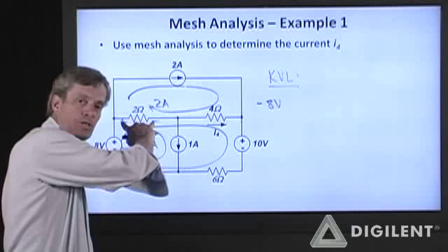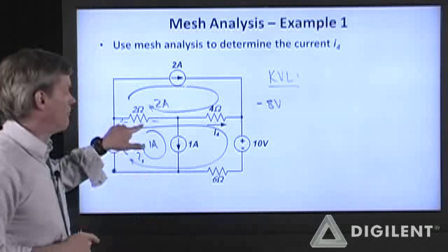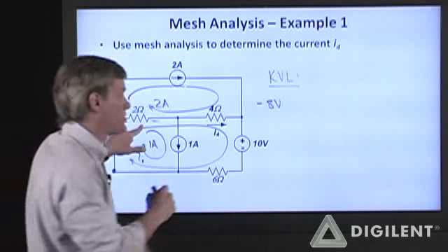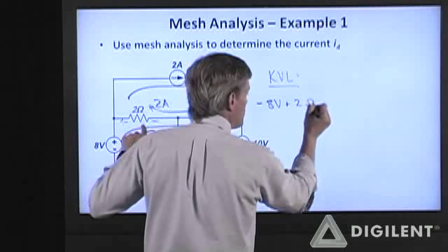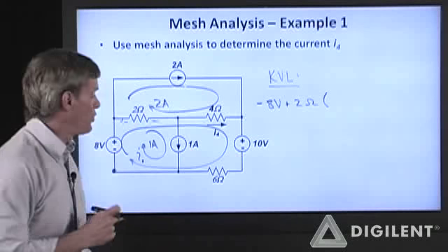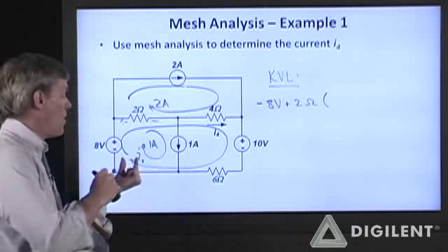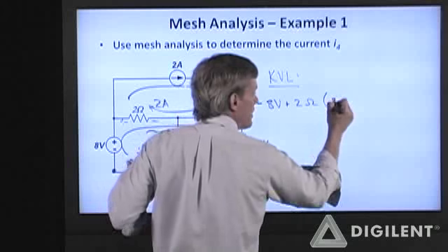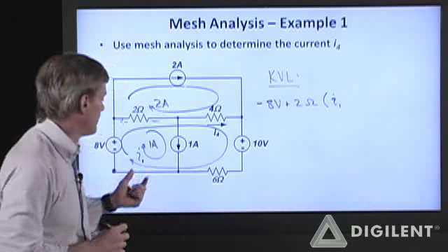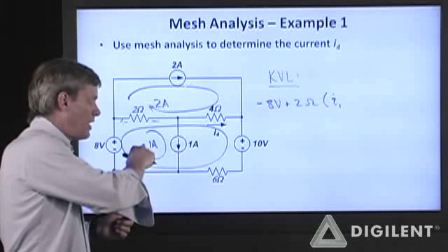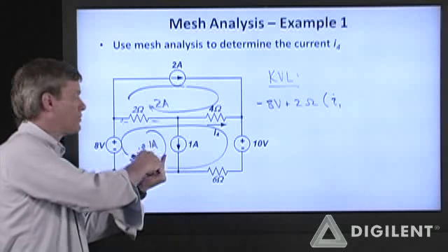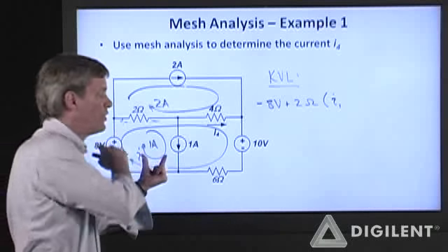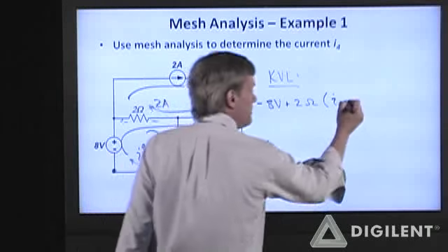Now I'm going to get the voltage across this 2 ohm resistor. Voltage is resistance times current. So I have a 2 ohm resistance times the total current through this resistor. Well, I1 is, of course, entering the positive voltage node, so it causes a positive contribution. The 1 amp current source is going to be entering the positive voltage node. It will be considered to be positive.